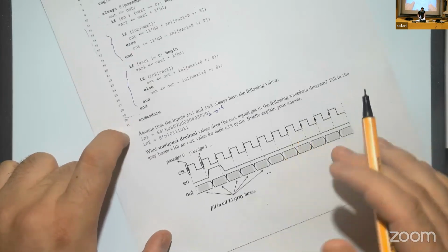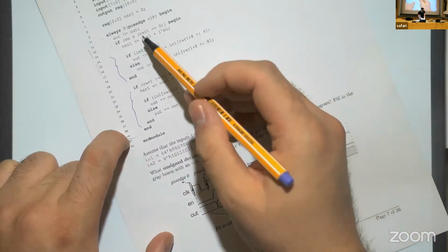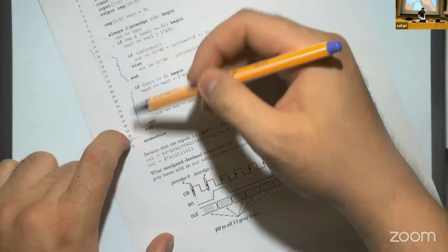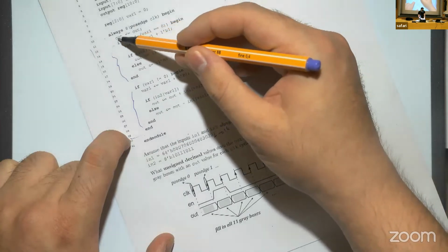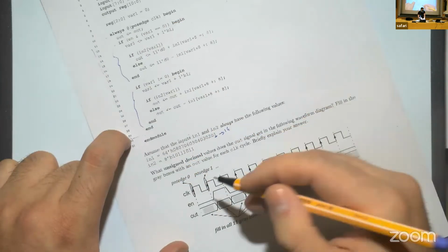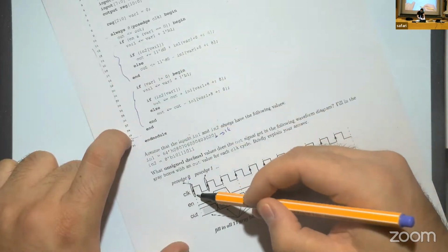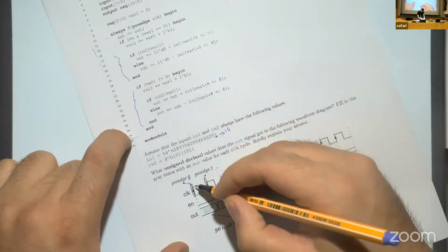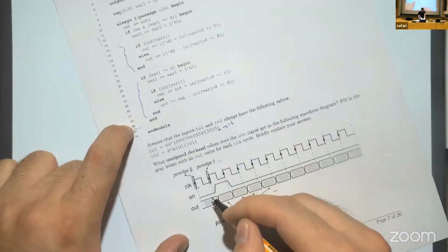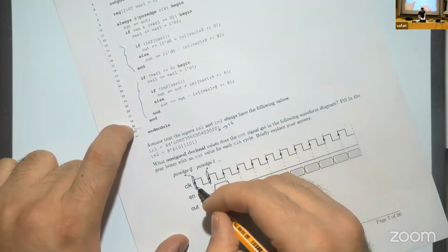Let's start. For the first one, this is posedge clock, right? And this is the always block. When we start executing this block, the variables assigned in this block are updated at the end of the cycle. So this posedge clock 0 will be executed here, but the results are updated after this cycle. The initial value is 0, so out becomes 0.